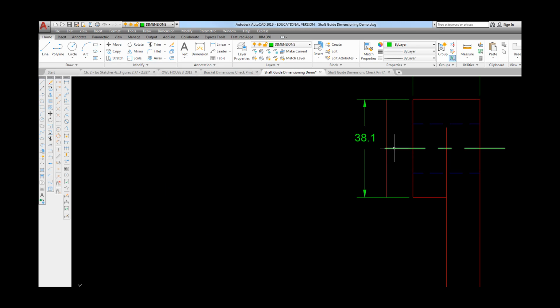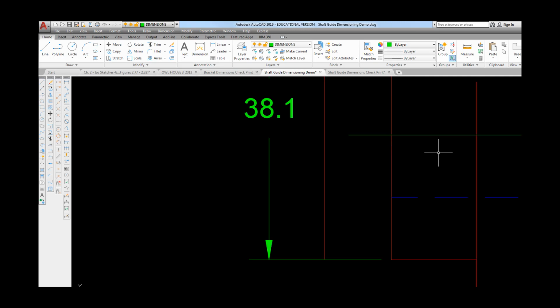And you can see that my extension line right here is coming out quite a ways. I'm going to move back in if I can with that guy. I think I have probably an object snap set on that. Let me come down here and turn my object snap setting off. Pick on that and move inside a little bit and pick. And if you recall, whenever we extend center lines out, we want them to come at least 0.25 inches. But the equivalent of 0.25 inches in a millimeter drawing or metric drawing is 6 millimeters. So as long as that extends out 6 millimeters, we're good.